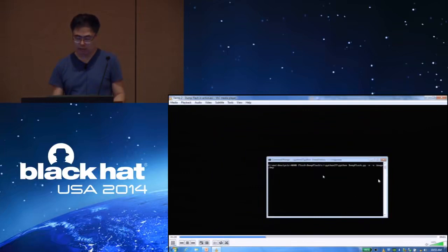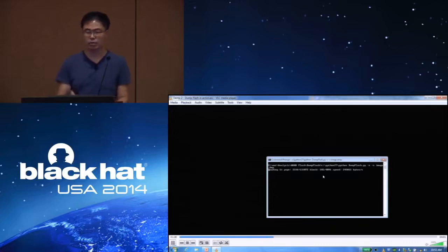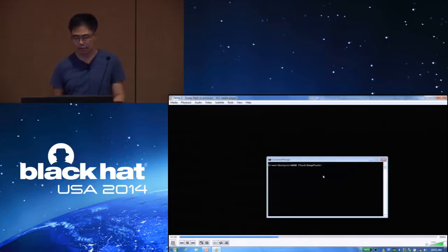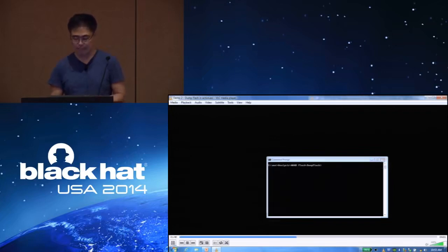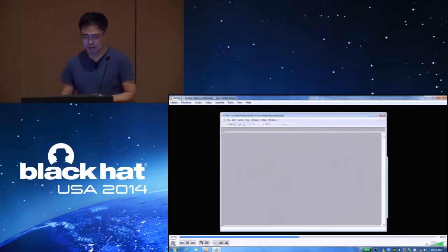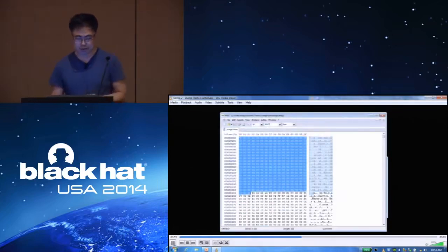And you can read by passing the -S option. In this case, the speed is really fast, 240K, but with the -R option before it was around 50K, so it's 4 or 5 times faster, because I'm using a special mode supported by Samsung. It supports a block read mode, so instead of reading page by page, you can read block by block. And in that case, the speed increases a lot. And you open up the image file again.